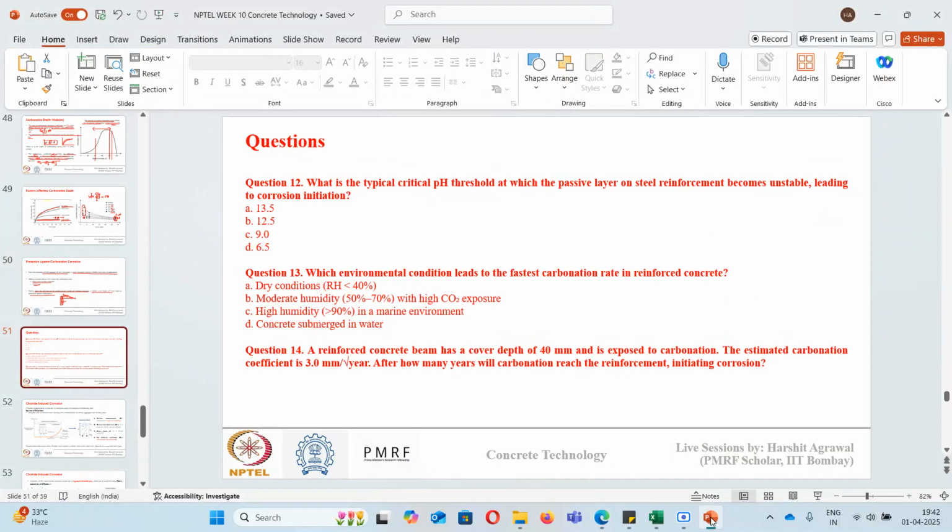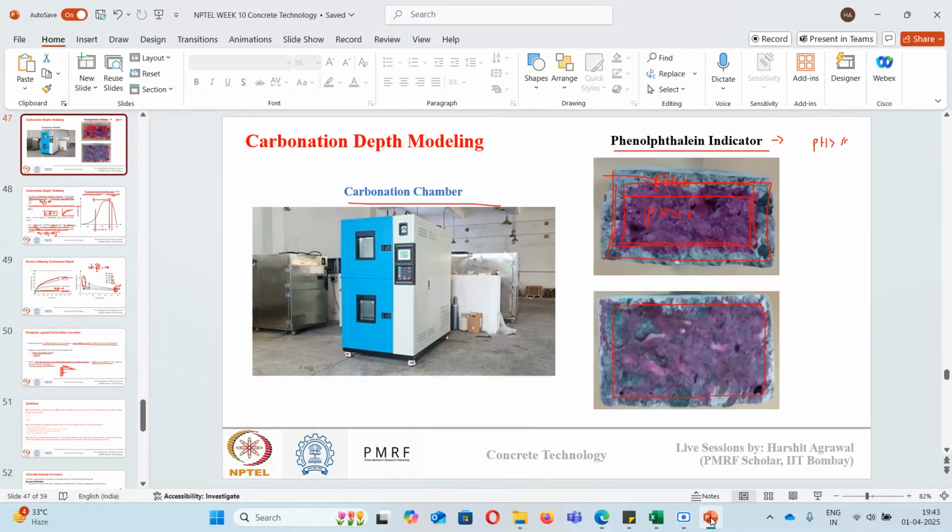The pH we measure is an estimation of pH. Generally, we can't quantify pH, because it is very difficult to quantify the pH of a solid system. If there is saturated concrete, then yes, we can quantify. If there is water inside a pore and we can dip a pH meter, then we can know the pH of concrete. But generally, when we are talking about carbonation, we just need to know whether the pH is alkaline or has become acidic, like whether it is highly alkaline or low, below 10.